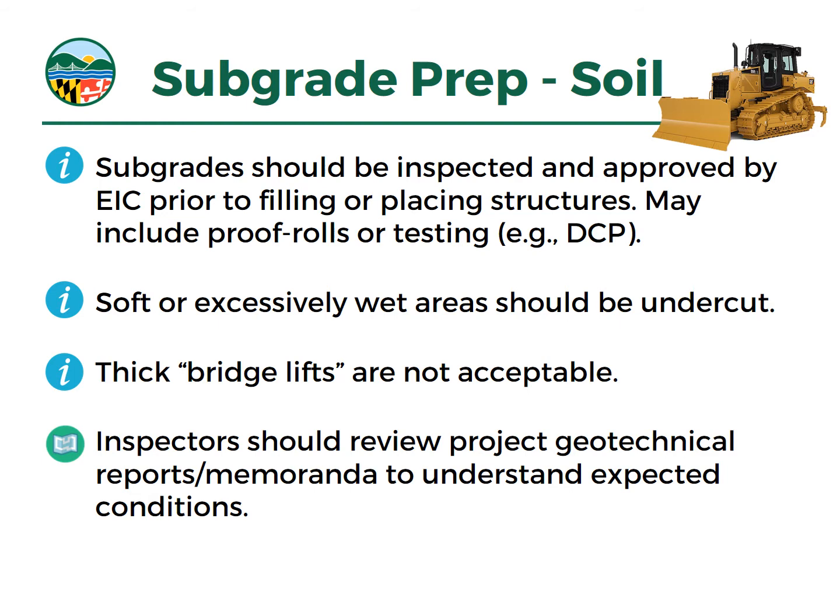We find that oftentimes, especially on dam retrofit projects, the subgrades can be really wet. You've had that water behind the dam for quite a long time. The subgrade's going to be very saturated. Or in new construction, you're digging down to a subgrade. Maybe you've intercepted a perched groundwater level. You're trying to put in a cutoff. But we don't want these really soft or excessively wet areas underneath the dam. They should really be undercut.